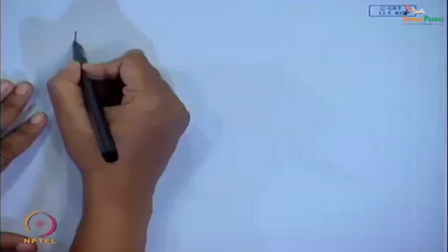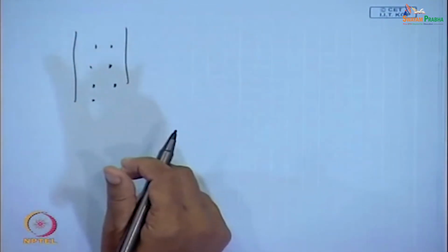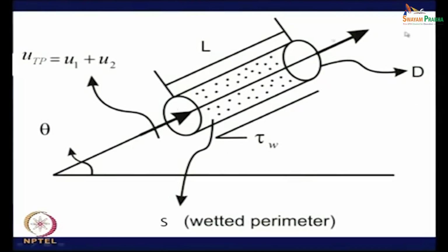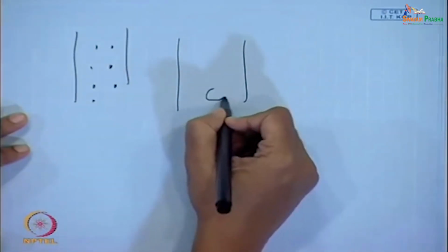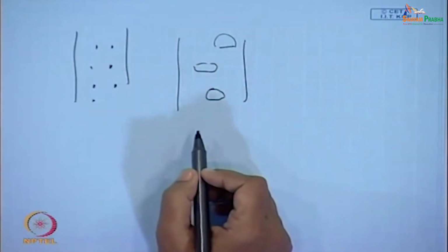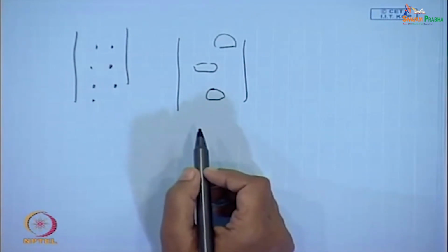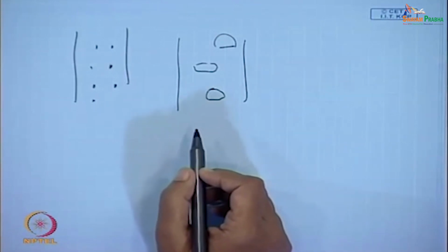Okay, it is not exactly bubbly, I should say dispersed bubbly, where the bubbles are dispersed uniformly. If you remember when I had drawn the pictures, this should be corrected as dispersed bubbly. That means the entire thing has this sort of appearance, this is the correct thing. Moment the bubbles become larger and they get deformed, the uniformity goes away. Under this particular condition also the homogeneous flow model does not apply, but we apply it, see how much deviation is there, and then we suggest some suitable correction factors.